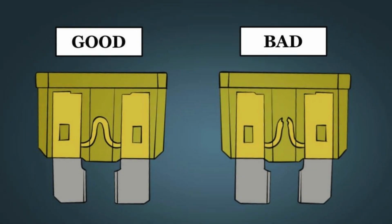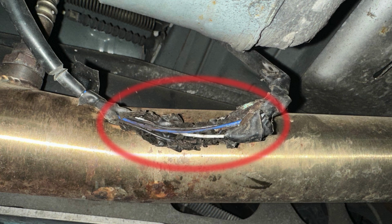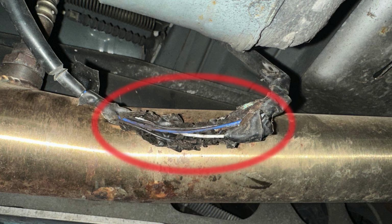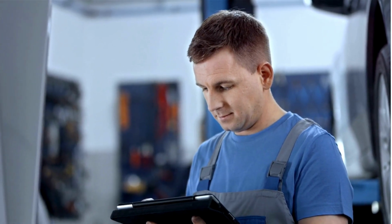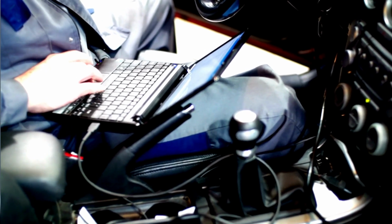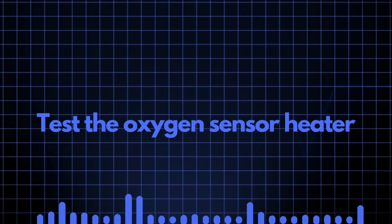Next, check the wiring around the oxygen sensor. Look for any broken or frayed wires. If you spot any damage, repair the wires and recheck to see if the P0062 code is cleared. If the fuse and wiring are in good condition, but the P0062 code persists. Step 3. Test the oxygen sensor heater.